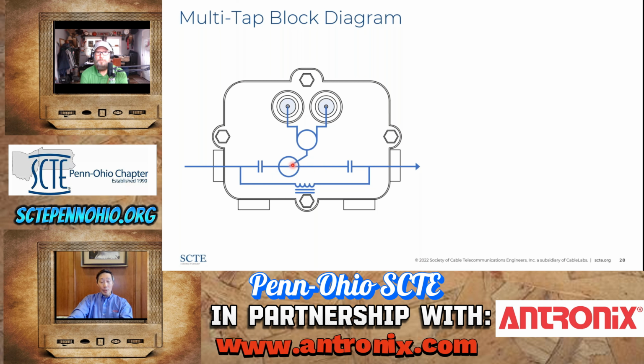And the tap port determines a dB value. This determines the loss going down to the splitter that splits it to this 2-port in this example. And AC is also shown from in to out, but it does not go down the drop port in a standard video tap.